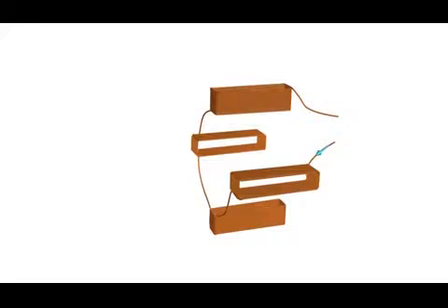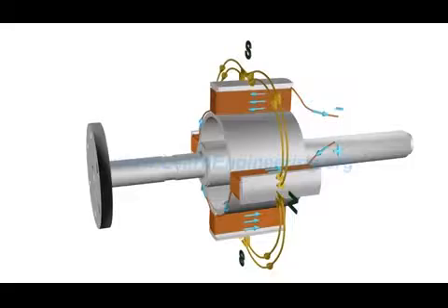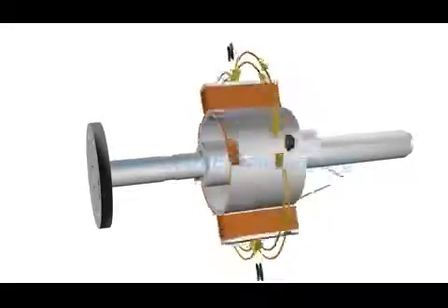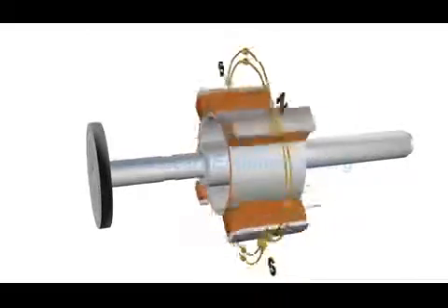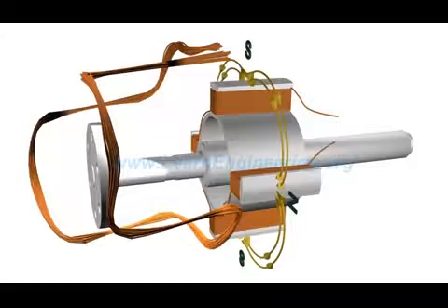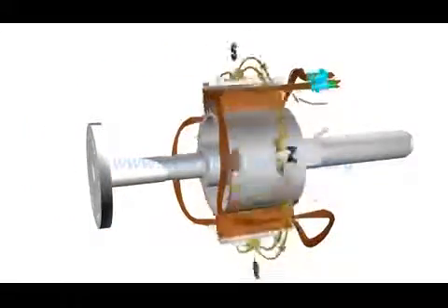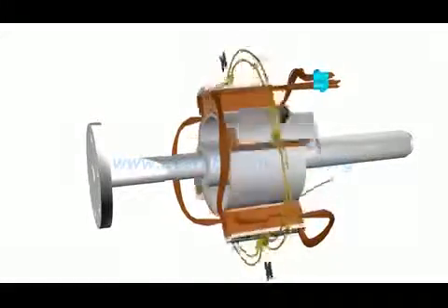Rotor coils are excited with a DC power source. Magnetic field produced around it would be as shown. The rotor is made to rotate by a prime mover. This makes the rotor flux also rotate along with it at the same speed. Such revolving magnetic flux now intersects armature coils, which are fitted around the rotor. This will generate an alternating EMF across the winding.